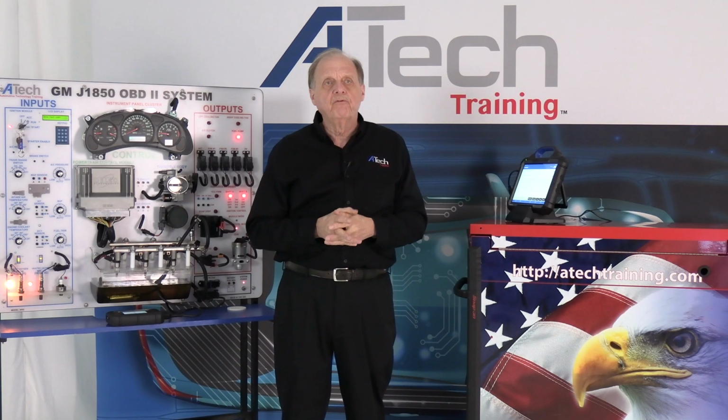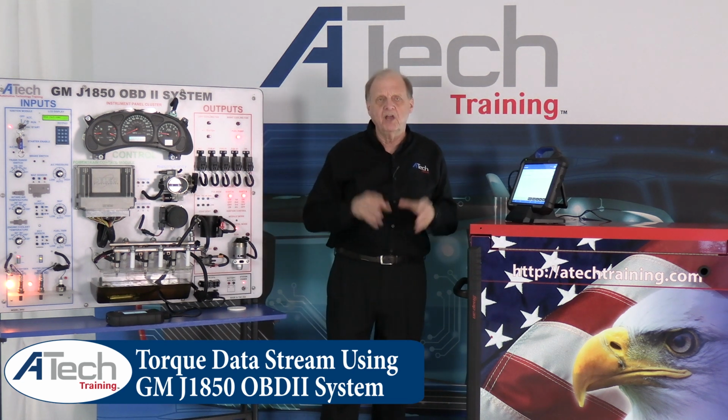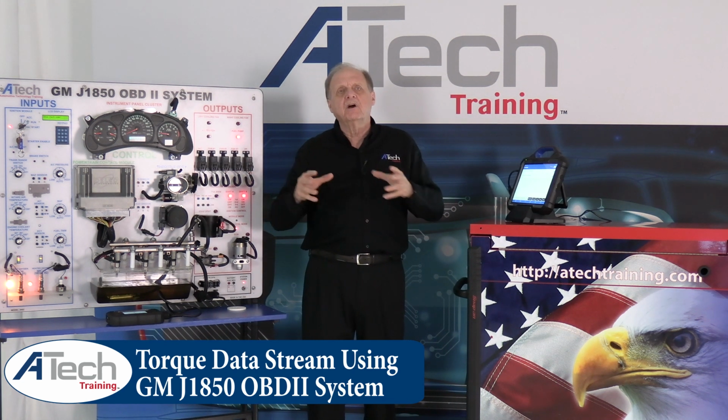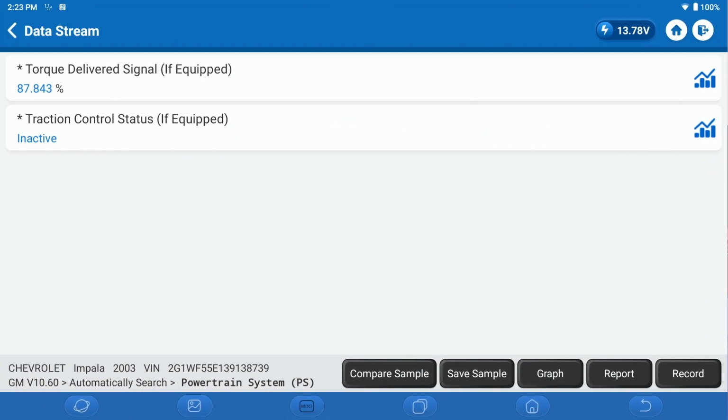When we're using this particular tool, remember I told you about torque. Torque engine management has been around for years, but we haven't really done as much as we should for it. So I want to go to the scan tool right now, and if you look, it says torque delivered signal, if equipped, 87.843. Notice it says inactive. That's something else that you want to start looking at on your cars. Look for the torque figures on there and start getting a database that you're going to use for later on, because it's been around since 2008 and most of us haven't been using it.